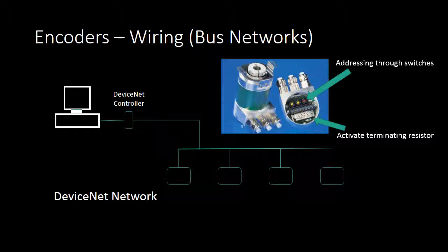For many bus networks, the encoder supplies absolute position only when interrogated by the controller. The bus may be configured to send data only on startup or on change of state. These methods cut down on bus traffic, but demanding a position update may take a few milliseconds. This may be a limiting factor if high accuracy is required.